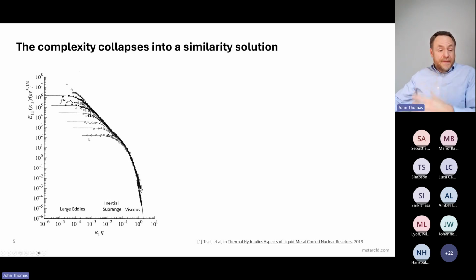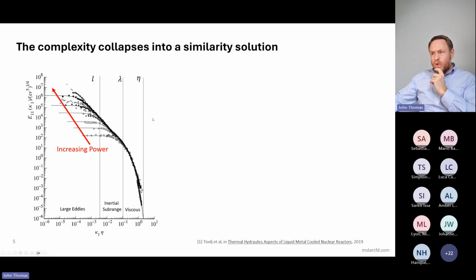Now, of course, some systems have more energy, right? You might have a faster moving impeller or a faster moving jet, so you'll have a greater total amount of energy inside that system, meaning you have more power, more energy being dissipated. But to be sure, the solution, especially in the phase space, is going to be self-similar, anchored to the Kolmogorov scale. The Kolmogorov scale describes the smallest eddies that exist inside the system, and this is linked just to Reynolds number or energy dissipation and viscosity.